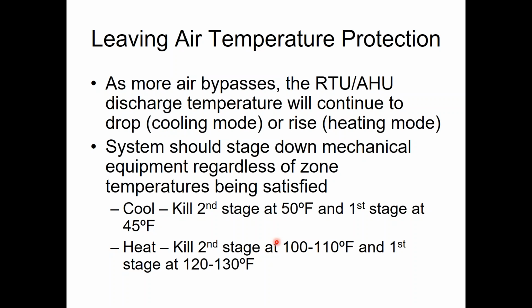the unit, right? For example, a gas-fired rooftop unit is going to have a high limit switch on there, so I can't get above a certain temperature, whatever that thing is set for, 140 degrees or 150 degrees, something like that. I don't want that to trip off when my bypass bypasses too much air. And it is going to trip off for sure every single week, no matter what. It is going to happen on a VVT style system.